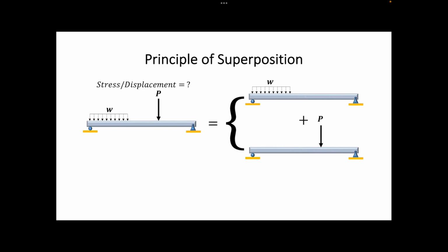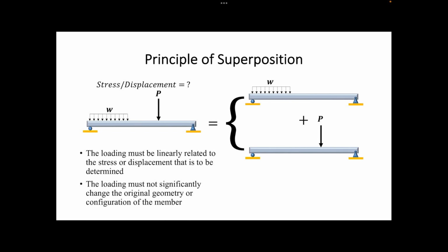Now, as you may guess, two conditions have to be satisfied to use this principle. First, the loading must be linearly related to the stress or displacement. Second, the loading must not significantly change the original geometry of the member.